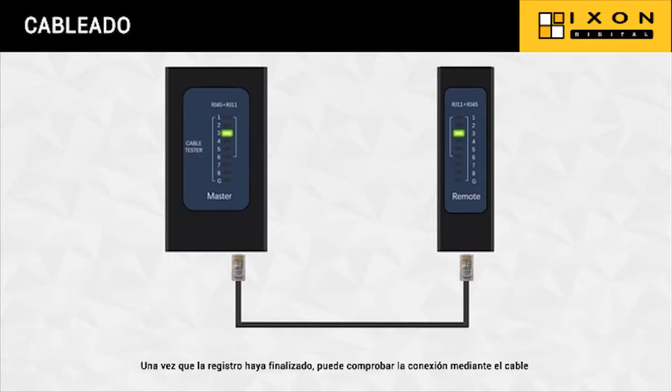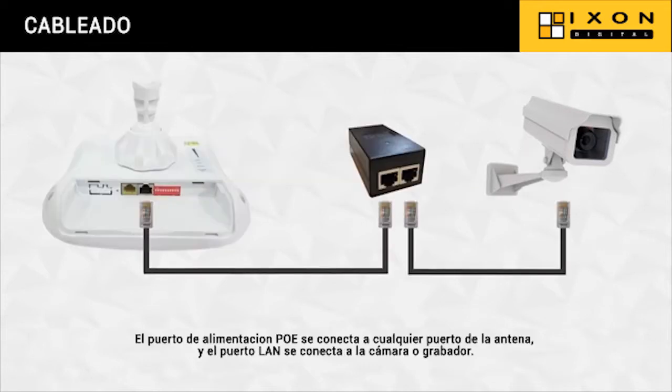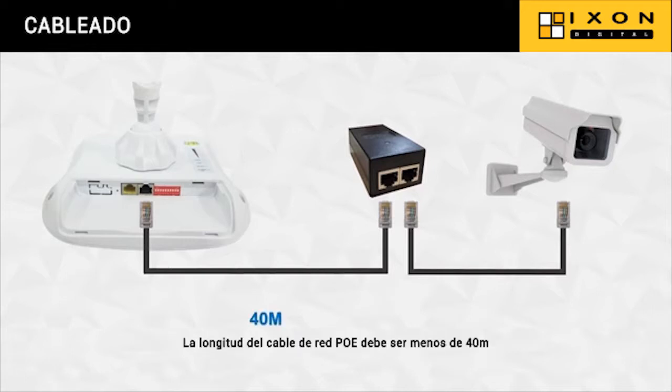After the AP is finished, you must test it with a cable tester. Before the camera is installed, we should connect it to the recorder for activation first. The power PoE port is connected to any network port of the AP, and the LAN port is connected to the camera or video recorder. The length of the power supply cable is less than 40 meters.